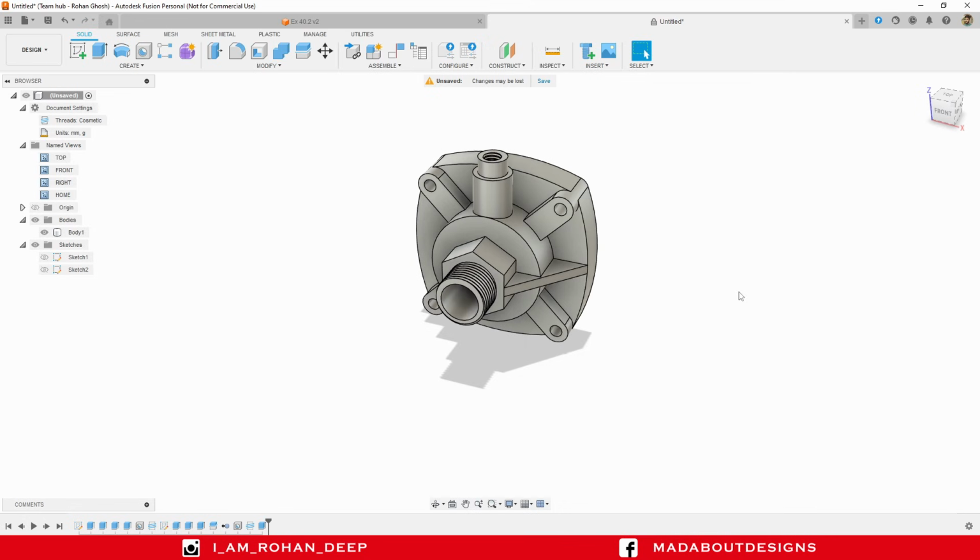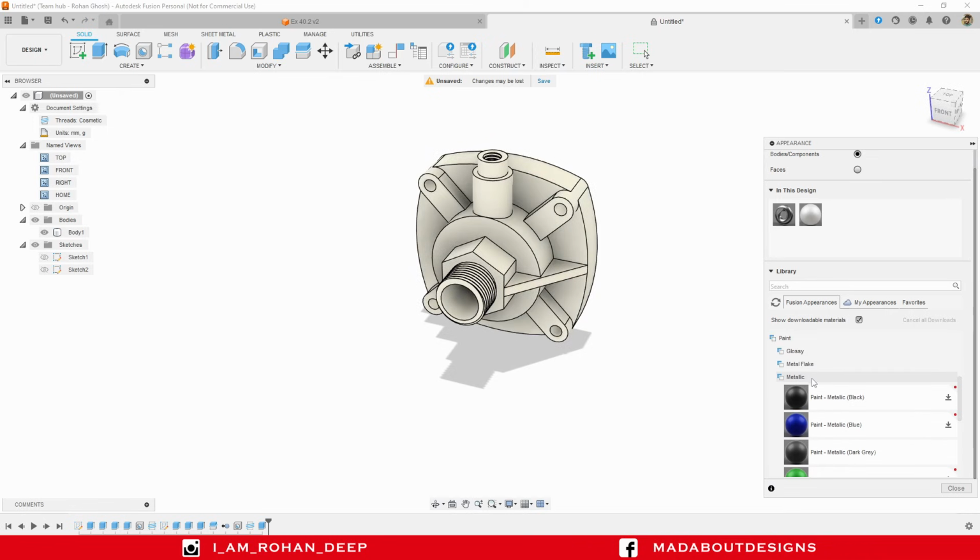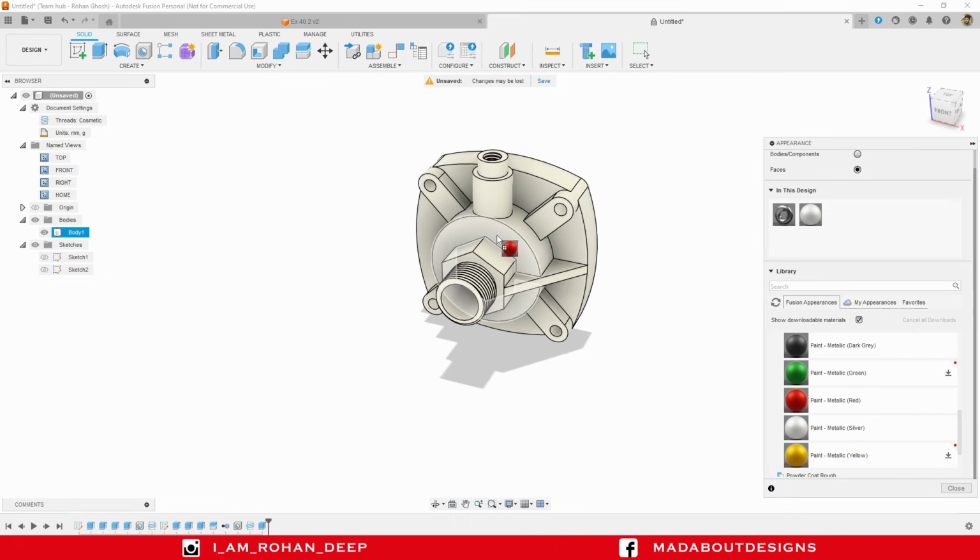Press A to go to appearance. I am going to apply this white metallic color on it from paint metallic, and if you want you can provide some colors also on the surfaces as like this. Just select the faces option.